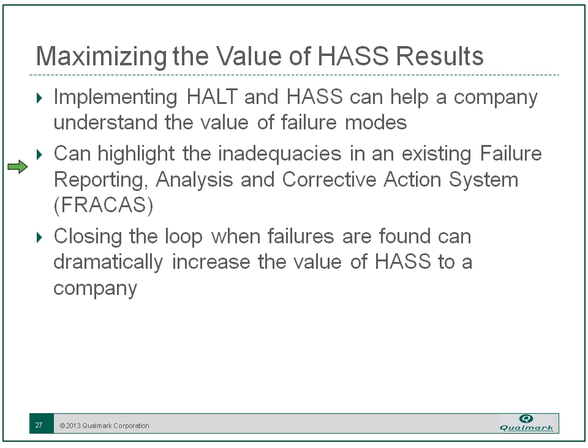And there isn't a concerted effort to understand what happens and get rid of it. With HASS, the extreme stresses that are used can show you the tails of a distribution that is shifting in your production. And if you take those red flag warnings and toss them in the trash can instead of getting them fed into your FRACAS and understanding what's happening with it, then you're losing a lot of the value that can come out of HASS.